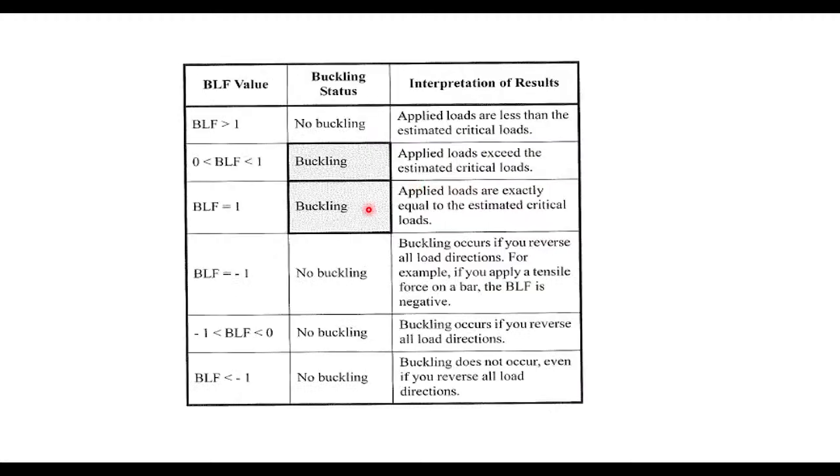Well, this is very important. If you get to know this particular chart and you understand the buckling results, the first thing is the buckling load factor. If it is greater than 1, your component will not buckle, because the applied loads are less than the estimated critical loads.